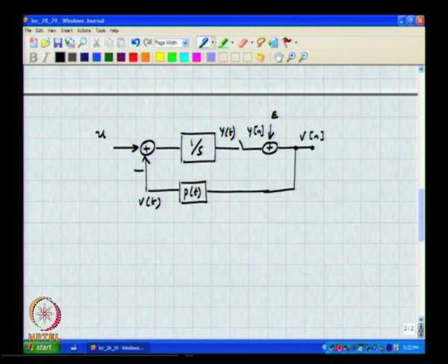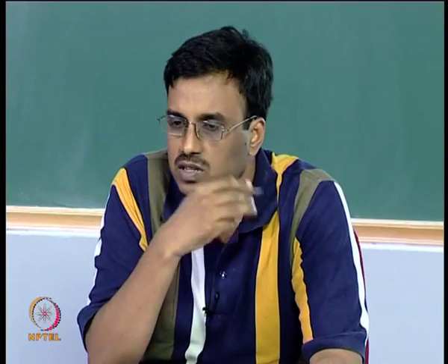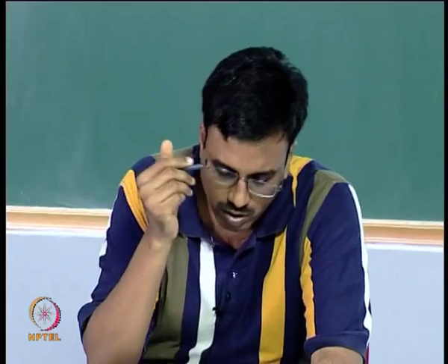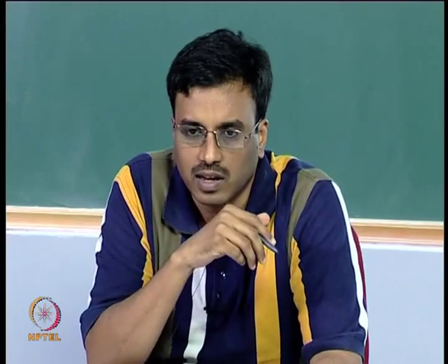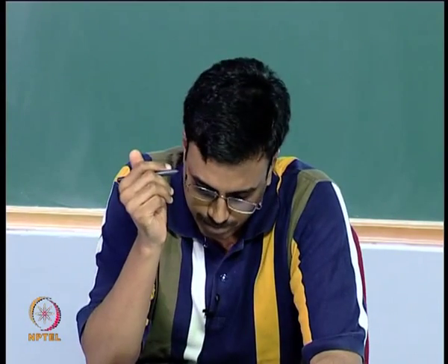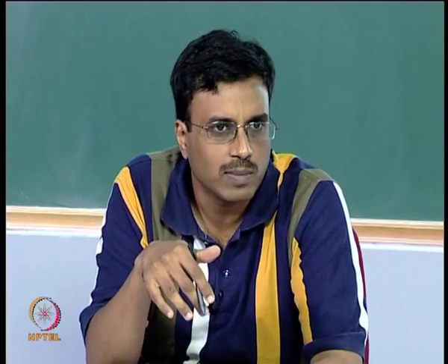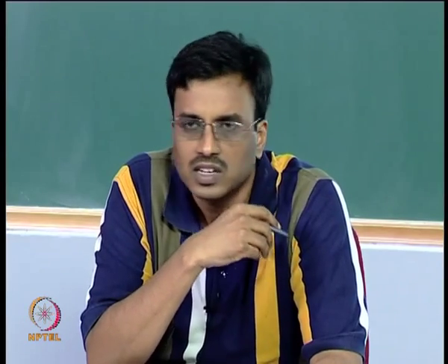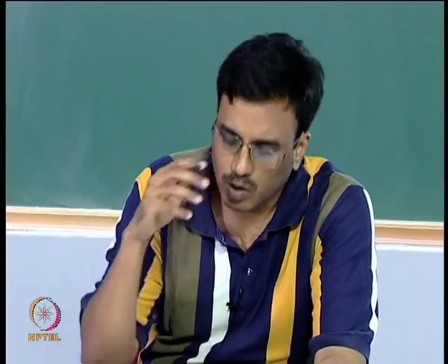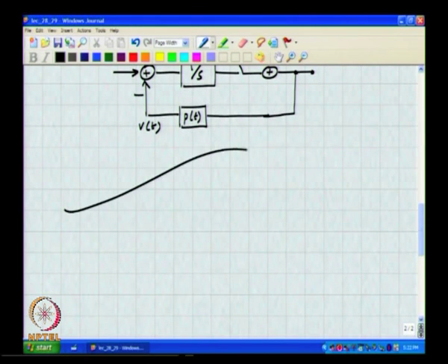All right. When we were analyzing the response of this modulator to continuous time inputs, the last time around we said that if the input is slowly varying, which is definitely the case, because by construction this whole thing is supposed to be an oversampling system. So, the rate at which the input varies from clock cycle to clock cycle is very small, right, in which case one can replace the continuous time input signal with a stepped approximation